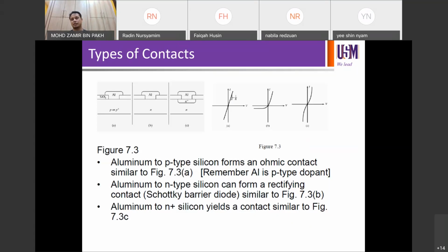Last time I told you that when you talk about doping, you can encounter a range of different doping configurations. It can be P on P plus, it can be N on N plus, it can be just P, it can be localized P plus on P, it can be localized N plus on N. It can be different configurations depending on the device.